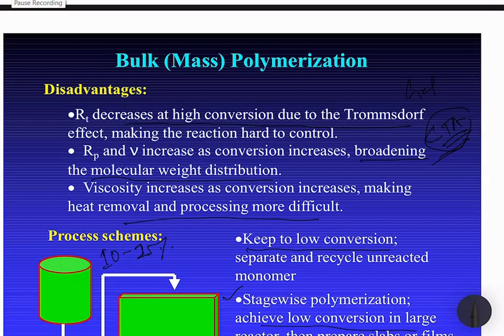And the chain transfer agent, as we have already seen, with a high transfer constant, resists the propagation and induces termination, and that way we can control the molecular weight and also prohibit the reaction from entering into the runaway mode. But that way we are actually terminating the reaction, meaning we are cutting short the molecular